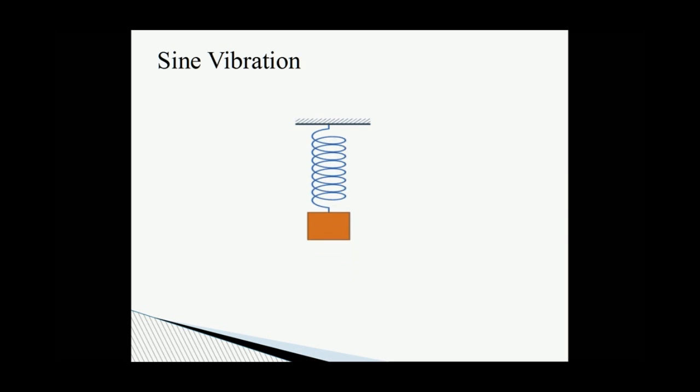Now let's go ahead and calculate the natural or resonant frequency of this spring mass system. Now, we're not going to use any math, except for division. It's going to be a very simple division problem. I'm going to keep track of time, and I want you to keep track of cycles. Remember, frequency is cycles per second. So you go ahead and start counting the cycles when I say go, and I will count the number of seconds. We're going to count to 10. You count the number of cycles within that 10-second period. Okay, let's begin. 1, 2, 3, 4, 5, 6, 7, 8, 9, 10.